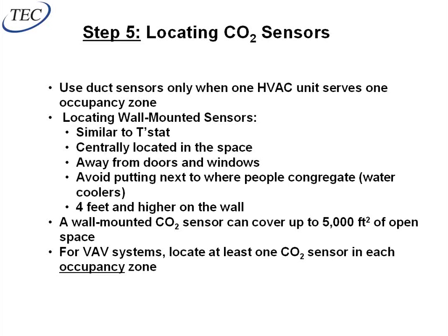Right? I typically do not want to put these things in the return duct. The return duct is going to give me an average of everything that's going on in all of my rooms. Well, if I have individual offices and then I got an open floor plan cubicle area and then I got a conference room and they're all in the same air handler, putting one sensor in the duct doesn't do me any good because it's always going to say I'm good, even though everybody just left their desk and piled into the conference room. Well, the system's delivering enough fresh air, which means the correct amount of CO2, but it's going to all these other zones that nobody's in, and it really needs to be directed over to the conference room where everybody just walked over to. So putting it in the return duct is a horrible way to control it in an office building environment.